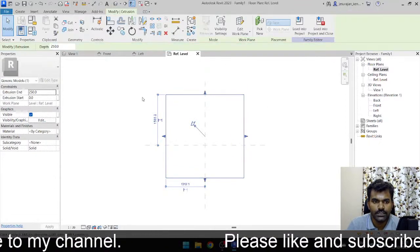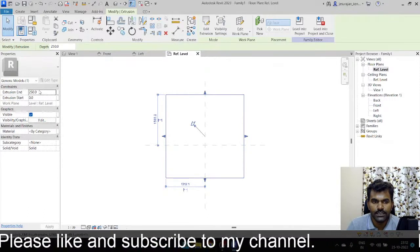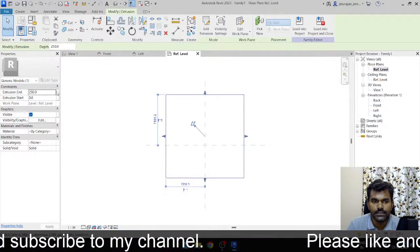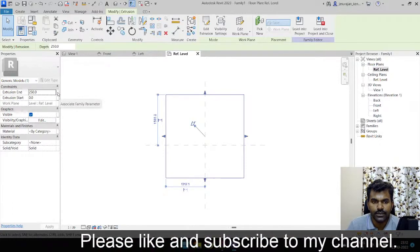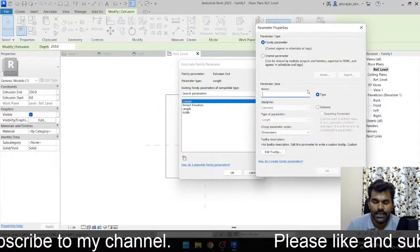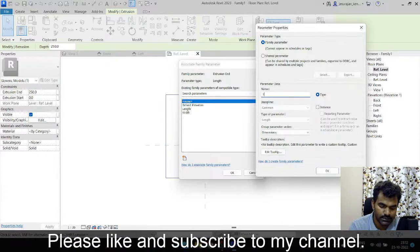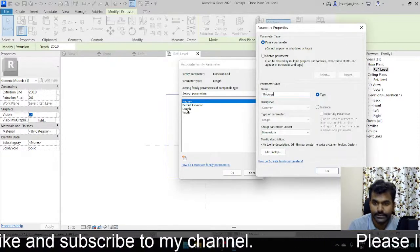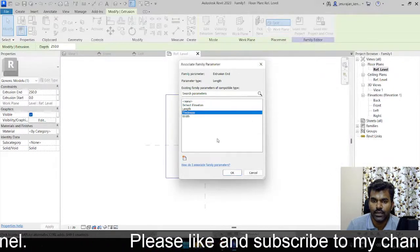Now you can see we have extrusion starting from 0 and ending at 250. If you click this rectangular button, you can assign a parameter. Let's take this as thickness, keep it as instance and say okay.